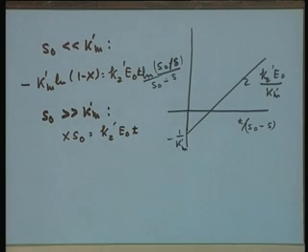Now, basically I think we must also appreciate that if you approximate an enzyme reactor to follow either a 0 order or a first order enzyme, knowing the values of Km and K2, the error involved in that will be determined by the ratio of Km to S0.